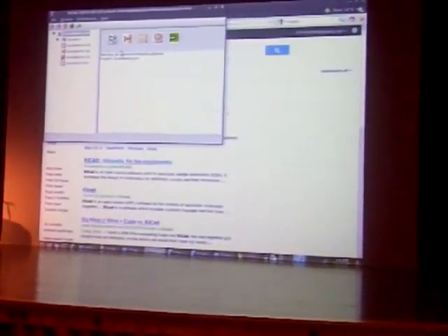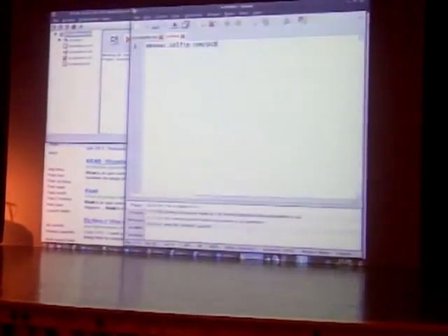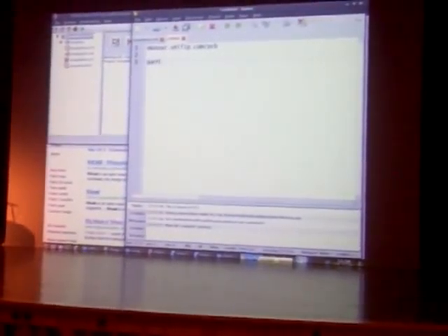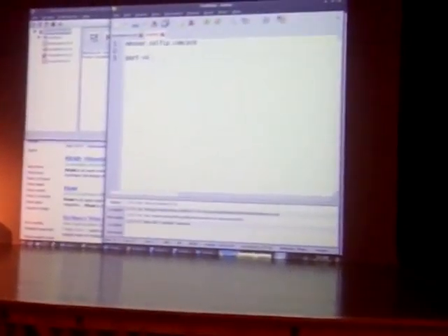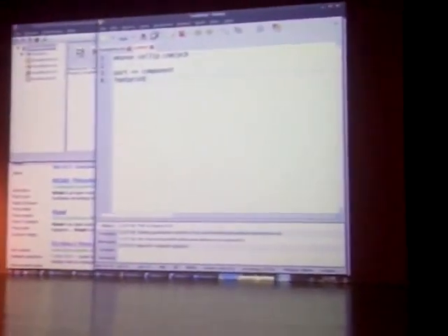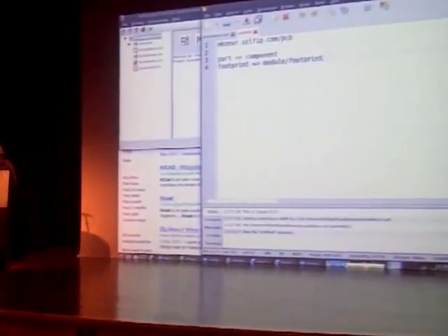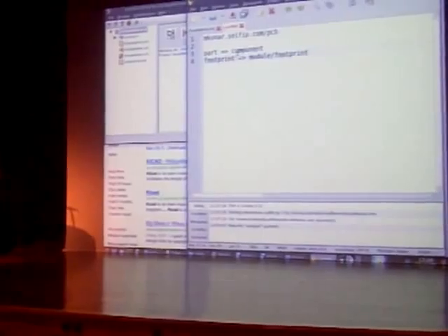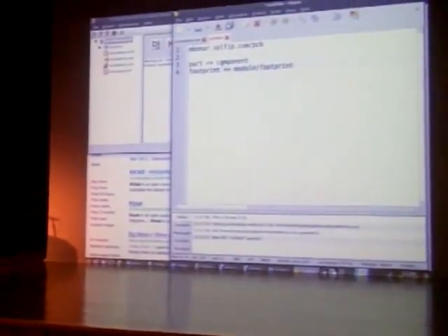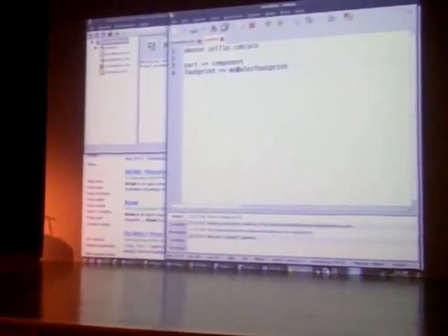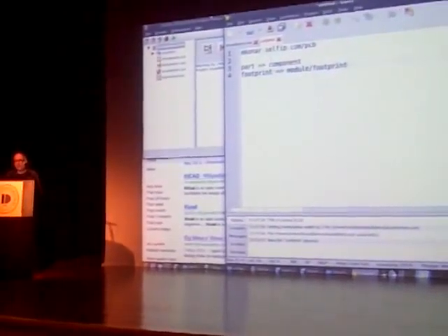One of the things about KiCad is the terminology that they use. What we've been calling a part, and what most people call a part, they call a component. And what we call, and what most people call a footprint, KiCad calls a module or a footprint. So components are parts, modules are footprints. Components are the things you put into schematics. Modules are the things you use to represent the things in schematics on your PC board.